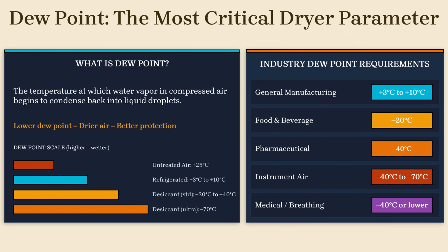Different industries require different moisture control levels. General manufacturing may operate with moderate dew points, while pharmaceutical, medical, and instrument air systems require extremely dry air for reliability and contamination prevention. Selecting the correct dew point is essential for protecting equipment, ensuring product quality, and maintaining long-term system performance.